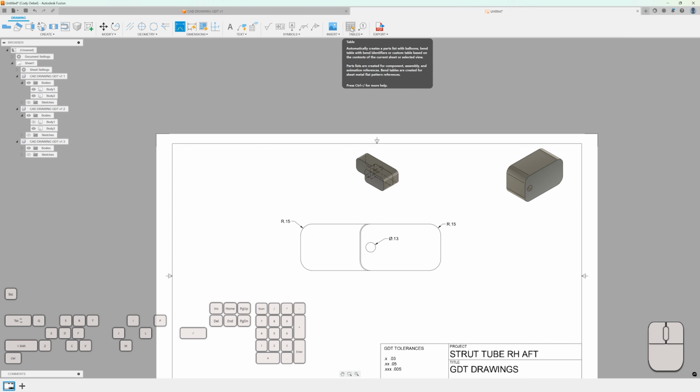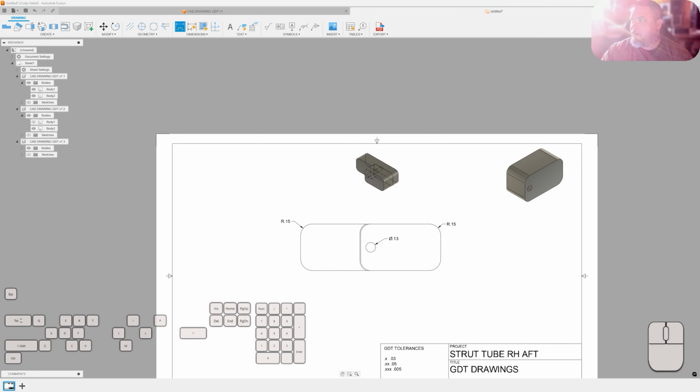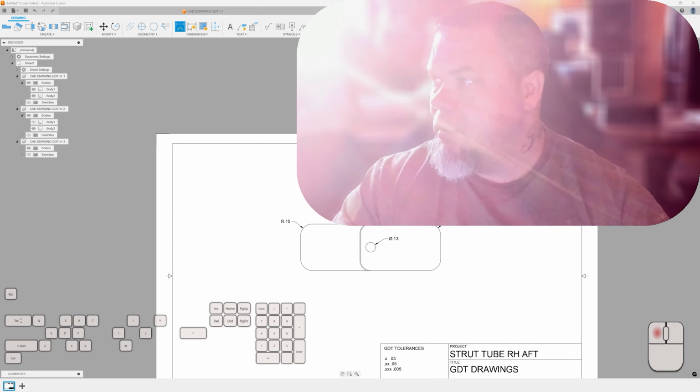You can put tables. Whenever I'm sending over a mold to China to have them injection mold things, I look at their data sheet, and then I'll create a table on my CAD drawing on the part, and I'll give some tolerances and material type and material data to provide the information that they're asking of me.